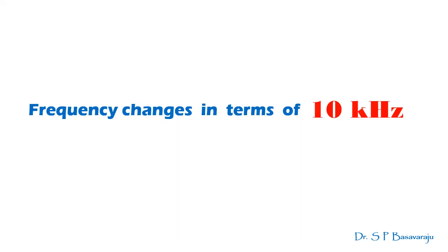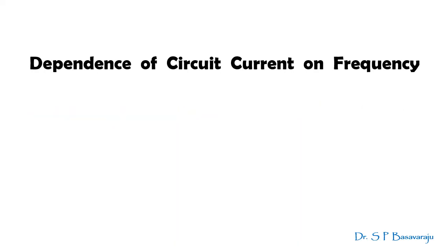What kind of dependence it is? Since equal rise in frequency is not resulting in equal rise in current, obviously the dependence is not linear. Is the dependence exponential? No. Then is it happening randomly? Not at all. A physical change always follows some kind of mathematical order. If you follow the kind of increase in frequency required to rise the current by equal amounts, it follows a particular pattern of increment which is known in mathematics as logarithmic. On this basis, we say the dependence is logarithmic.